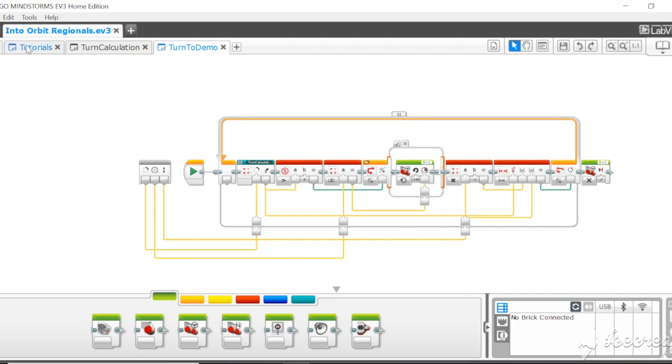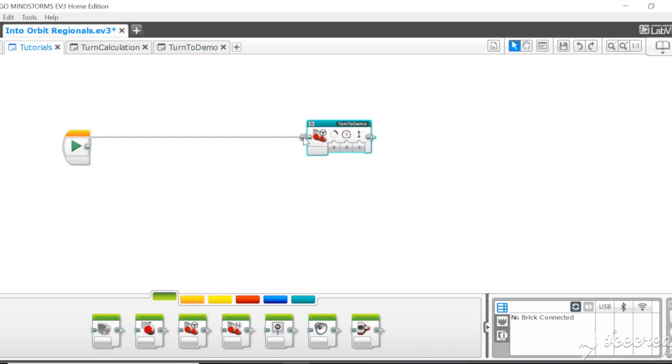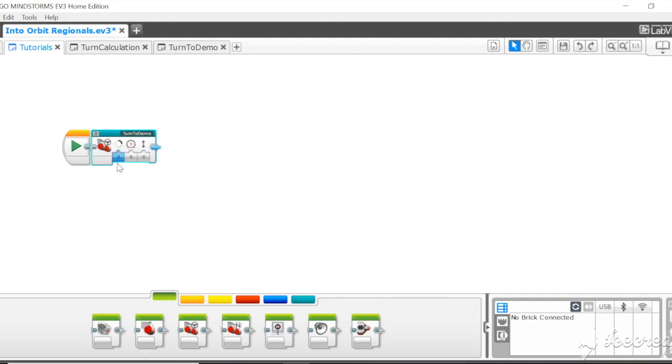So now you can use this basically whatever you want. So you can say turn to an angle of 90 degrees at a speed of 30 with an accuracy of 1, and it'll turn to wherever you want. Now the other thing is, if you put it on too much speed, it does have some problems. So we suggest no more than a speed of 30, and keep an accuracy of about 1 or 2, and only use 2 if you are up near 30.